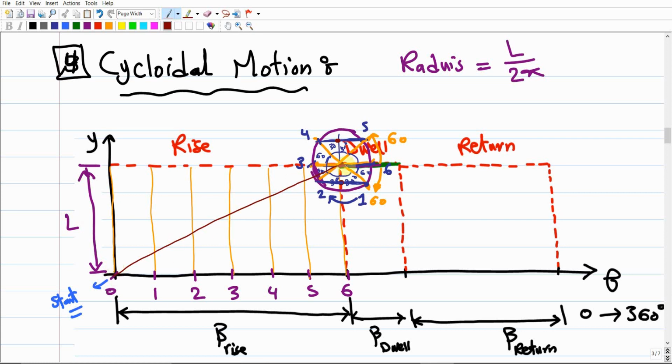We're going to do the same for the segment 4, 5 and the segment 1, 2. So we're going to take the midpoint of the segment 4, 5 and just draw a line. We won't connect it to anything; we just draw a line that is exactly parallel. You have to use the Aristo triangle to make sure that this line is exactly parallel to the first line that we drew. That's why this middle line should be the first one drawn, because we're going to use it as a reference to be parallel to the other lines.